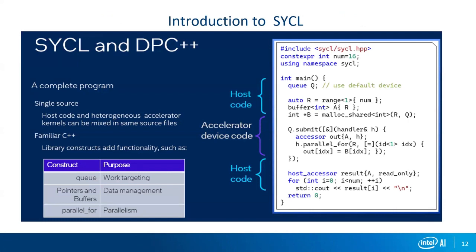So now let's move to the interesting topic where we are going to talk about the SYCL semantics. The most important part is understanding what SYCL is. So SYCL is a language, first of all. It is an accelerator interface language which you can use not only for CPUs and GPUs, but also FPGAs and different other hardware vendors. The main important part of SYCL is that it has two different aspects. One is the host and one is the device. That means parts of the code are going to run on the host and part of it is going to run on the device. There are three uniquely, severely important concepts over here, known as command queues, memory or the pointers and buffers, and asynchronous parallelism, heterogeneous parallelism.